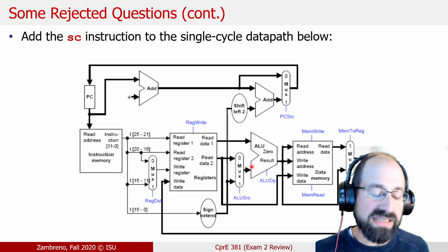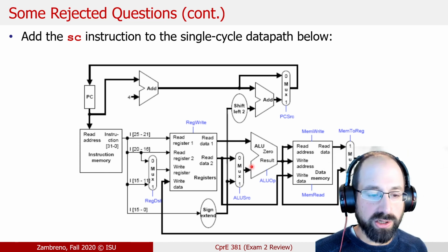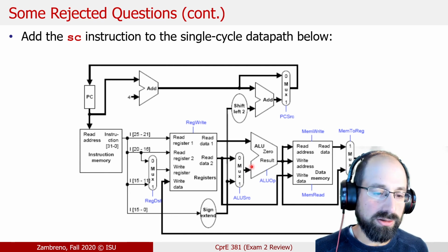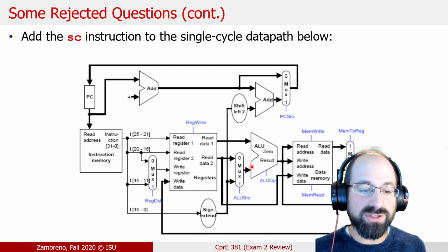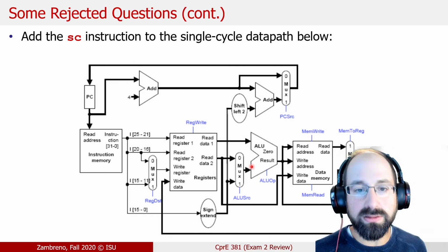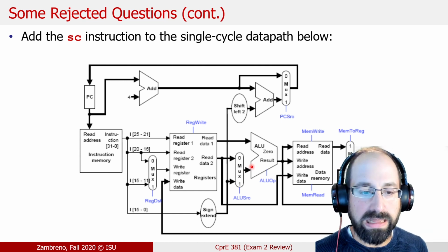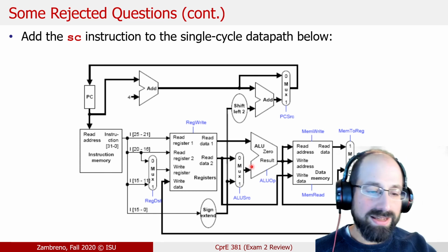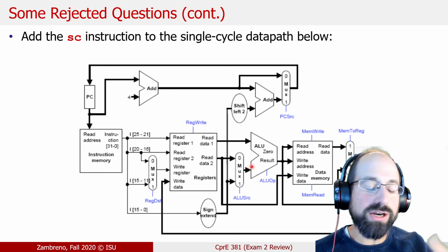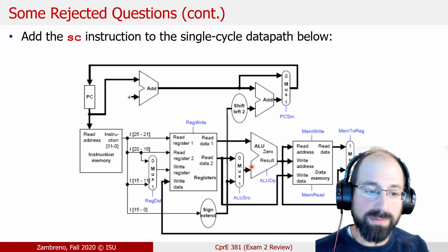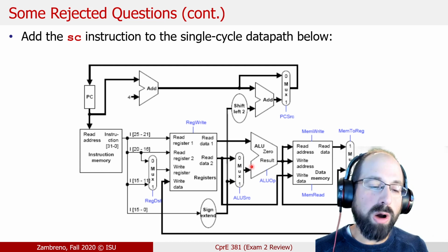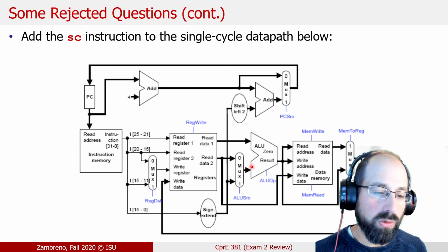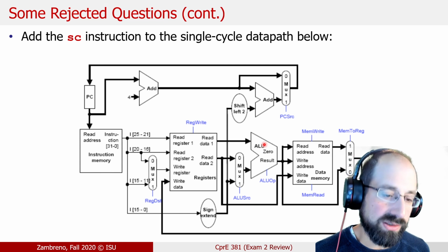And that would be an example where you would be supporting this instruction with basically 0 overhead in terms of re-architecting your data path, right? It would just be a very specific set of control signals corresponding to this instruction that would drive the existing muxes that you have there. So your answer would have to speak to that. What new elements would be needed? Do we need a new mux? Where would that new mux, if we needed it, be connected? And then what would be the values of all the other control signals in your design in order to support that new instruction?